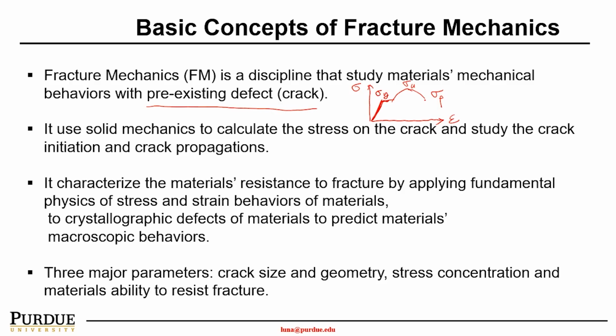Fracture mechanics uses solid mechanics to calculate the stress at the crack and study crack initiation and crack propagation. So if I have a material and it starts to develop a crack, when the material has a crack during its service life, it may not be dangerous.